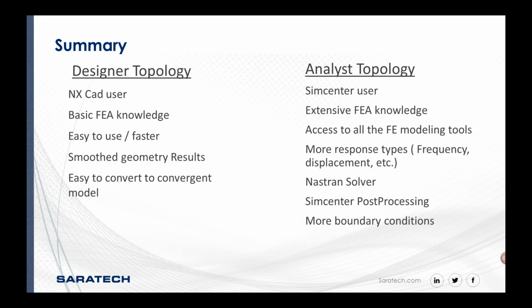If you are using the analyst topology, you are a Simcenter user. You have extensive FEA knowledge. You have access to all the FEA modeling tools. You have more response types: frequency, displacement, stresses. We didn't have all those in the designer topology optimization. It uses the Nastran solver, solution 200. So maybe a requirement makes you have to use some solution like that.